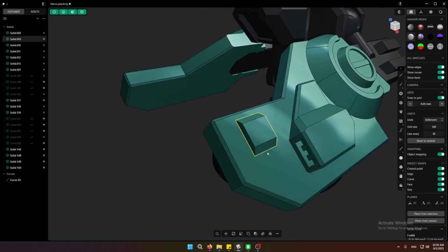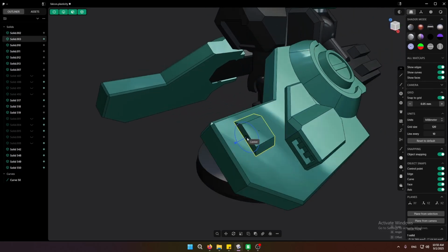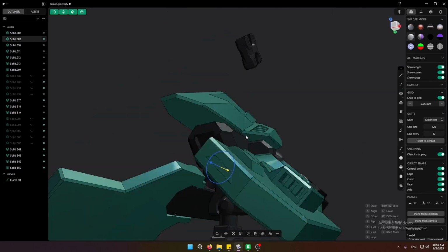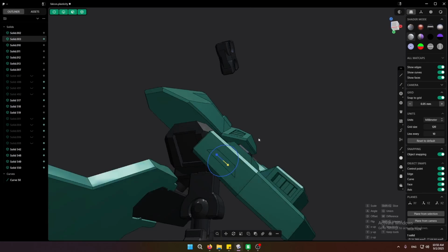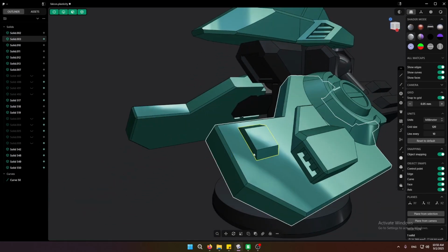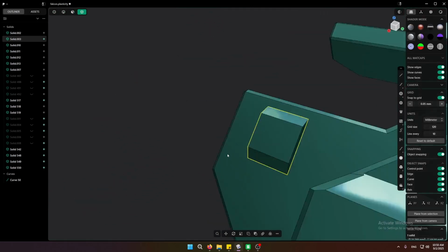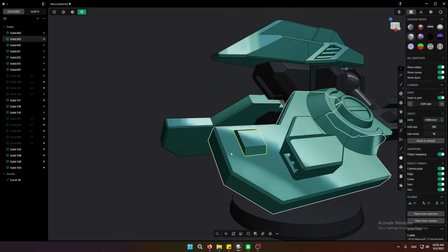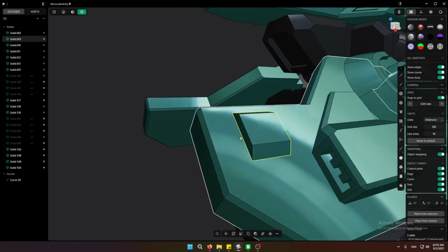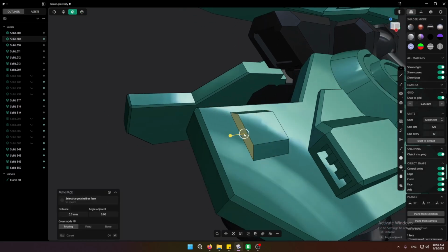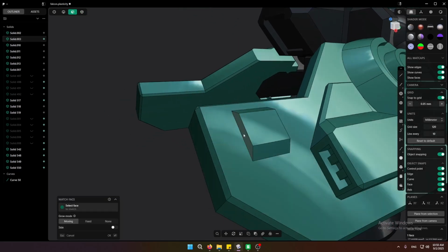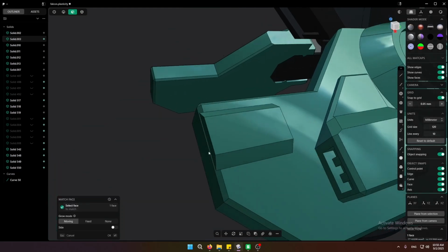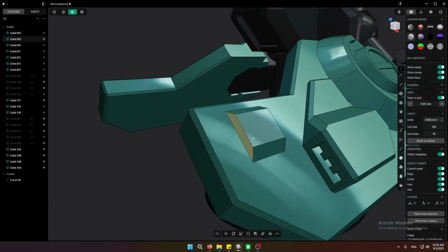Now you might have heard that you can align things in Plasticity by hitting Control D, selecting a face, and placing a duplicate of the object on the face you want. But there's a problem. This is going to move the piece around, and we don't want that. Say, what if I want to align this little thing to the end or a tip of this wing sort of shape? Well, what I could do would be to take this face and hit K to match this face to this. But this would change the actual shape of the object.